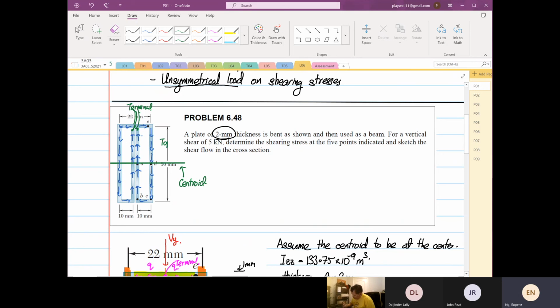If you look at the top, we know down here there's a gap, they're not really connected. At the top it is very easy to do: the shear flow only goes one direction if we want to find the stresses at point D. But at the bottom, we have flow coming down in one direction, then going towards the left, and then it goes up again.